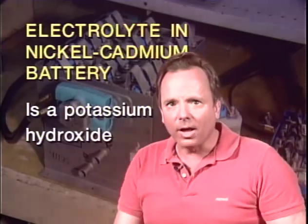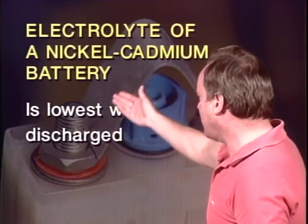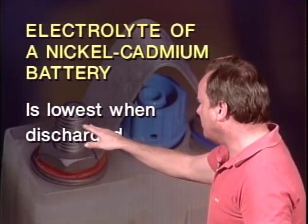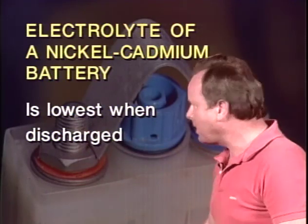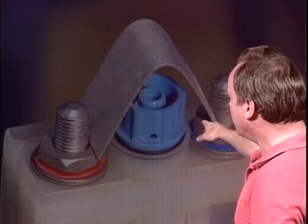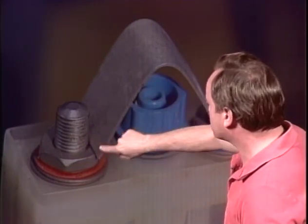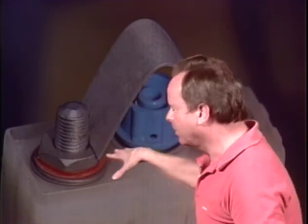Now, the level of electrolyte in a NiCad battery is low sometimes. Let's take a look at when the level is low in a NiCad battery. And the answer is when it's discharged. The level is lowest in a NiCad battery when it's discharged. By the way, you might be interested in what we're looking at here behind us. This is a NiCad cell, one cell out of a battery that is being strapped off to short it out to make sure that it's completely discharged before it's charged.